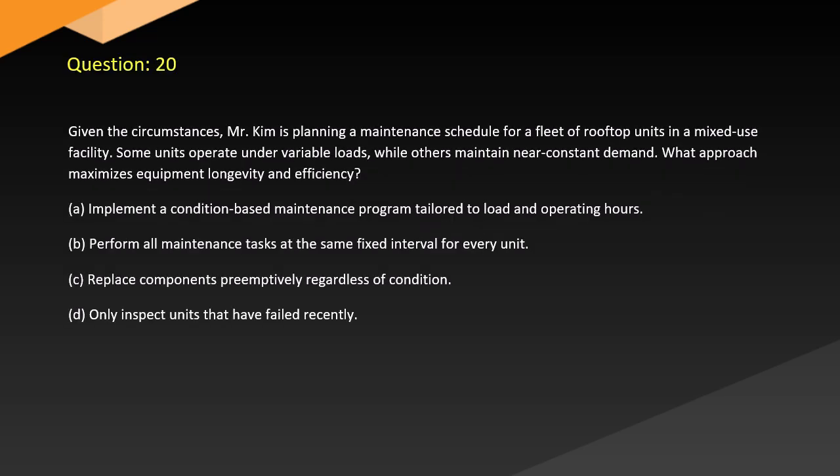Question 20. Given the circumstances, Kim is planning a maintenance schedule for a fleet of rooftop units in a mixed-use facility. Some units operate under variable loads, while others maintain near constant demand. What approach maximizes equipment longevity and efficiency? A. Implement a condition-based maintenance program tailored to load and operating hours. B. Perform all maintenance tasks at the same fixed interval for every unit. C. Replace components preemptively regardless of condition. D. Only inspect units that have failed recently.